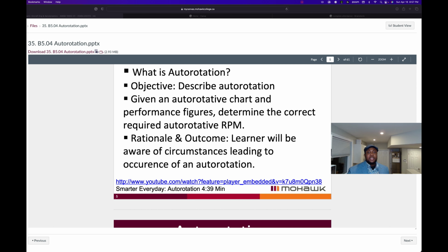Rigging. There's something that we do when it comes to rigging the system in the flight controls and rigging that collective, which you can see here in the picture on your right. Most helicopter collective controls are rigged in a way that at their normal gross weight, which is expected, the collective will have to be raised slightly to keep rotor RPM during autorotation. So it's not rigged to be put down completely, but you want to be able to raise it up just a little bit so that in the event that we need to, we are able to get a little bit of increase in speed where needed.